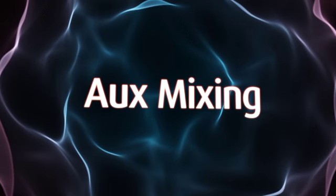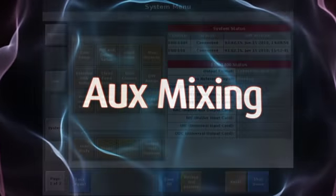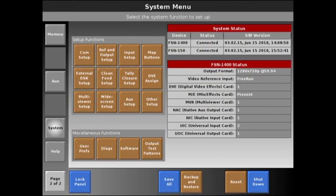Aux mixers are highly effective for using the switcher in the presentation world, where all you really need to do is mix from one source to another or cut from one source to another. Large screen matrices can be switched with one button by recalling presets and storing the various previews. The biggest benefit to the Aux mixers is that they free up the traditional mixer effects buses in the switcher so that you can use those for your records or outputs that require more effects like picture-in-picture or advanced keying.